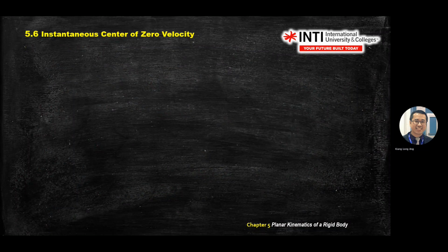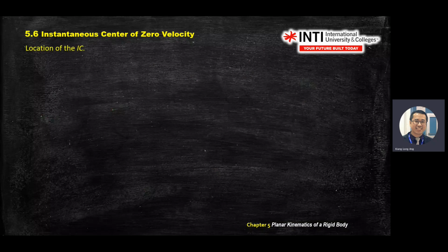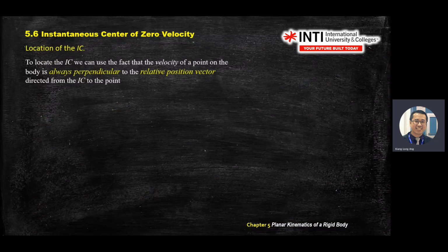Next, this is one set of calculation on rigid body. Now we show you another set of calculation. I prefer this one actually. This is also my favorite. So we will look at one location called the instantaneous center of zero velocity, meaning from the diagram itself, we build another reference point, stand on that point, and then see what happens to the body.